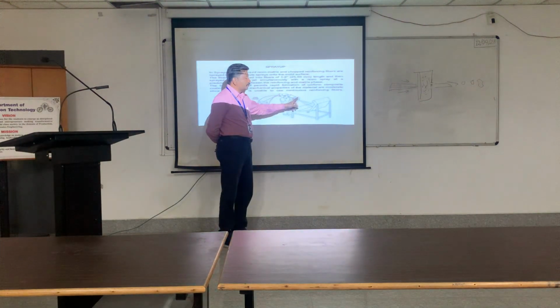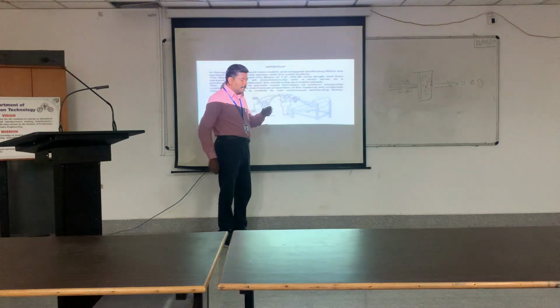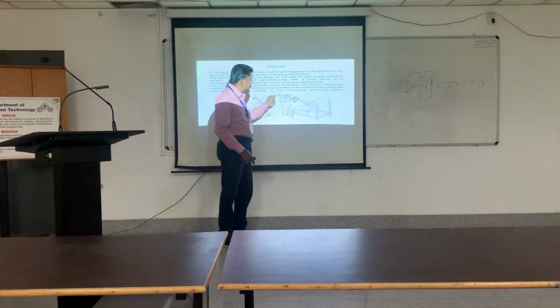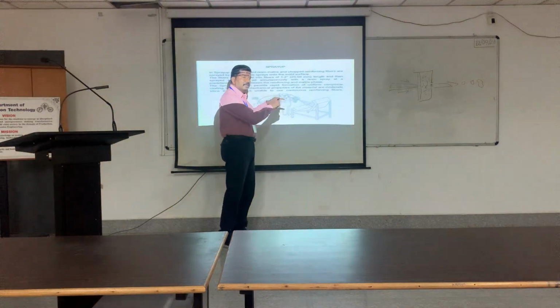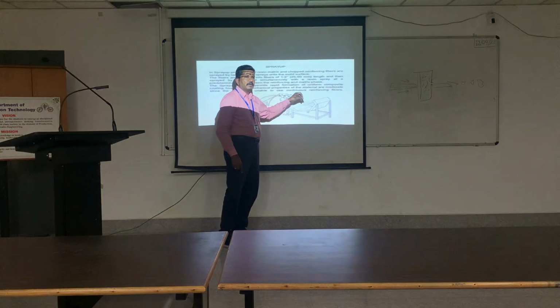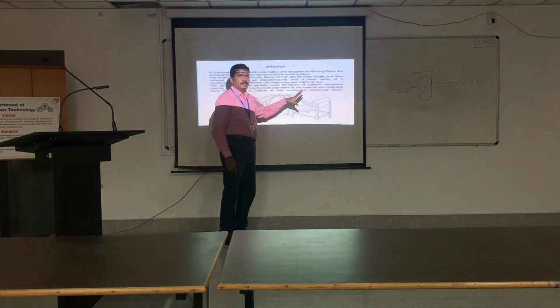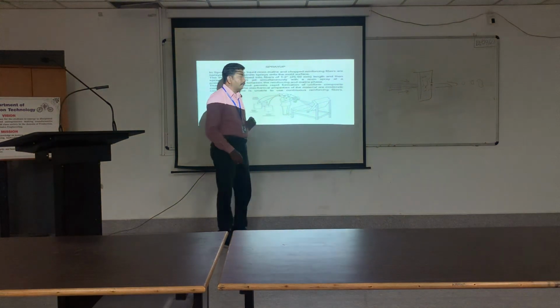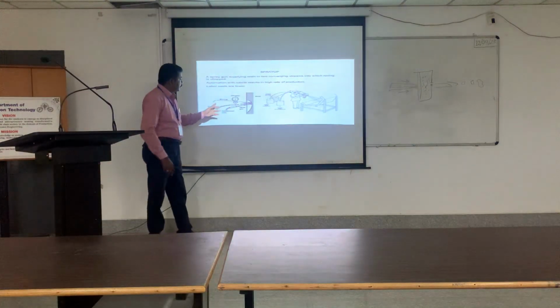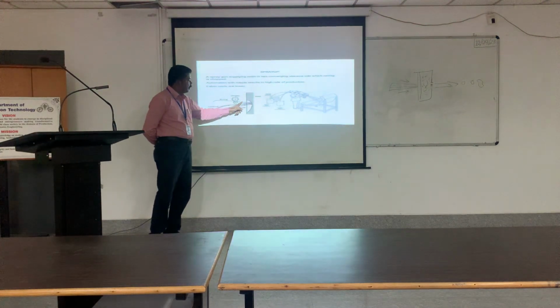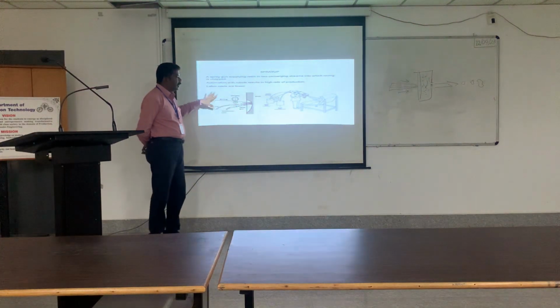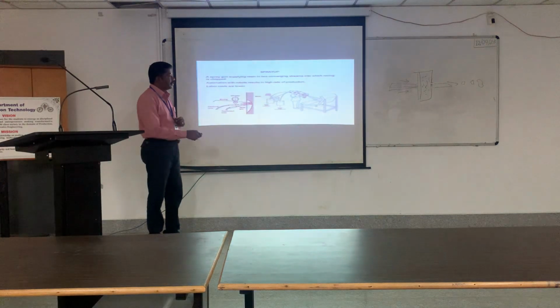It will be similar to a motor, with a cutter section. This long fiber will be cut into smaller pieces, these two liquids will come here, everything will be mixed, and the mixed composite will be spread on the table or the mold or whatever. You can see the illustration. This is the chopper. The continuous fiber comes here, the cutters cut it into smaller pieces, spread on the rollers, and the catalyst and the resin mixture will also be there. Or in some cases, all the things will be taken in a single tank also, right? And that will be sprayed.